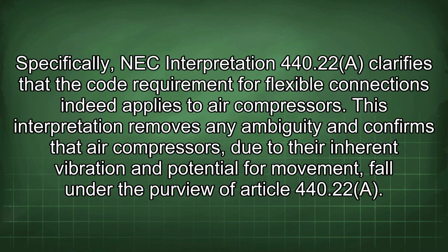Specifically, NEC Interpretation 440.22 clarifies that the code requirement for flexible connections indeed applies to air compressors. This interpretation removes any ambiguity and confirms that air compressors, due to their inherent vibration and potential for movement, fall under the purview of Article 440.22a.